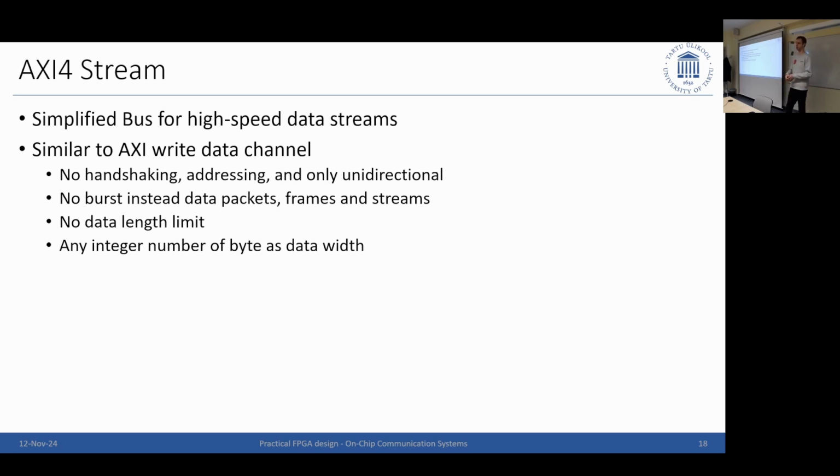So this goes onto the protocol level then. On top, your data identifies what is the start. If you have an image, you would send a beginning of image, a header, the image data, potentially a footer, maybe some checksum, and then an end of image, and this would be facilitated on that level and not through the communication bus itself.